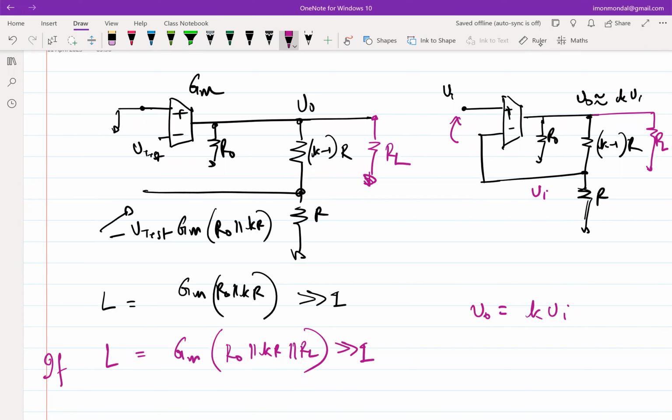Okay, fine. So now we can look at this same thing from another angle, from the perspective of output impedances. If you have a voltage controlled voltage source, its output impedance should be low, high, what? Low, should be low. So does that mean this contraption that we see, when we find Rout, is approximately equal to how much? It will be approximately equal to 1 over GM, right? Not actually 1 over GM, but of that order.